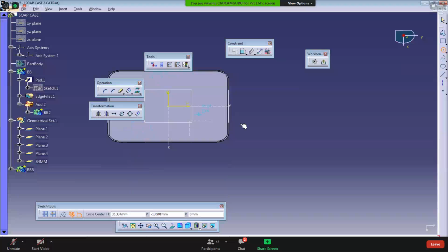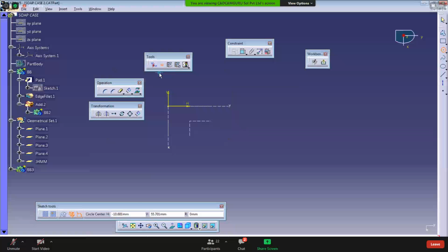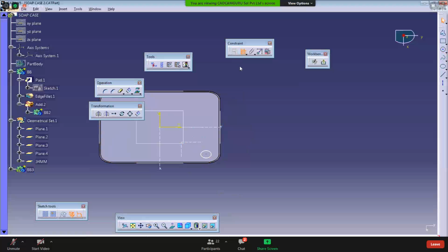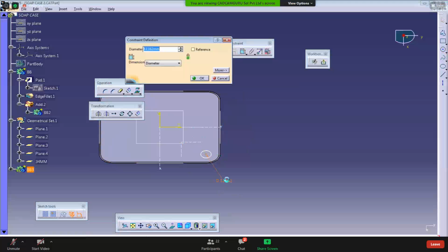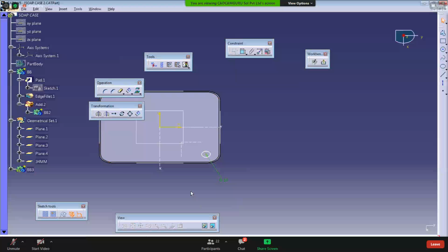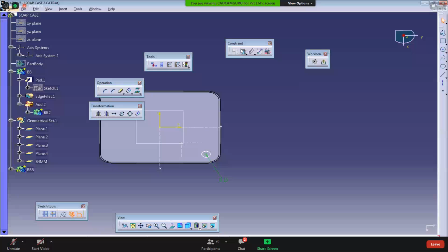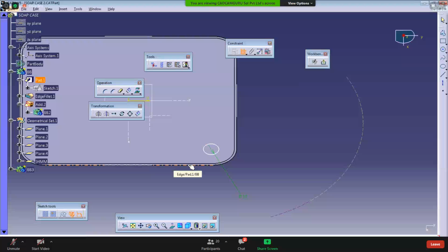Where is that tool? Okay. So something here at this location. What is the diameter? 10. So define that size 10. What is the location? 20 by 22. Am I right? So 20 from this plane. Do not take this line because we are taking the previous body reference. Do not take body references. Always take the planes or axis reference.